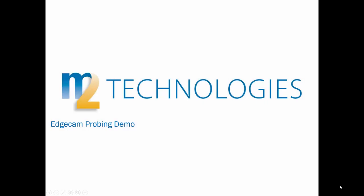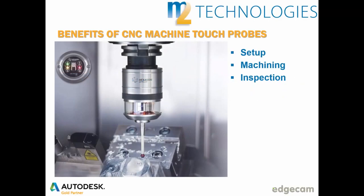Welcome to this brief demonstration of Edgecam's probing capability. Touch probes on CNC machines can be used for a range of tasks, such as to assist with component setup, to measure features for in-process machine adjustment, or verifying finished component dimensions on the CNC machine. Used properly, touch probes contribute toward reduced CNC machine setup time, improved part quality, and increased productivity.